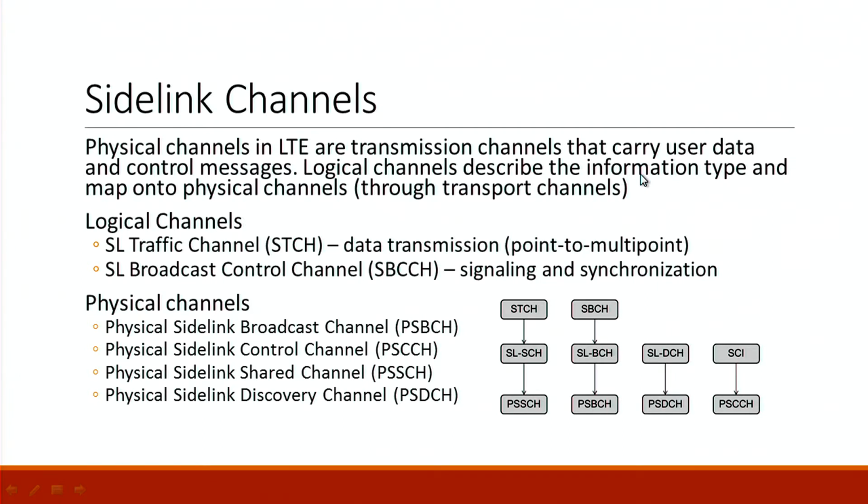So first of all, resource allocation: you need to be notified of what resources you are given. Normally in LTE, resource allocation happens using the physical and logical channels. Yesterday I talked just about physical channels. Physical channels tell you how you structure the bits that are used for a specific purpose and how you map them into resource blocks on the LTE resource checkerboard that we saw yesterday.